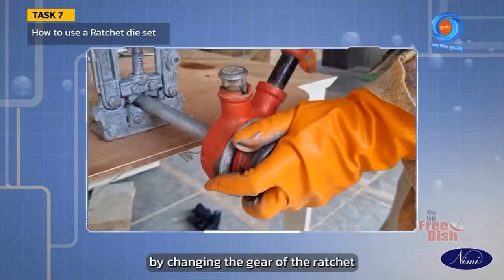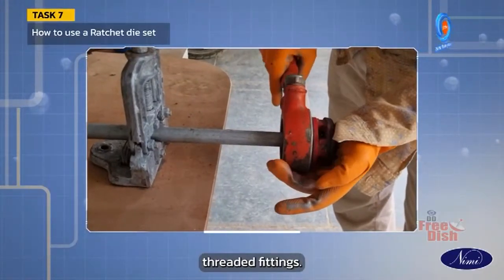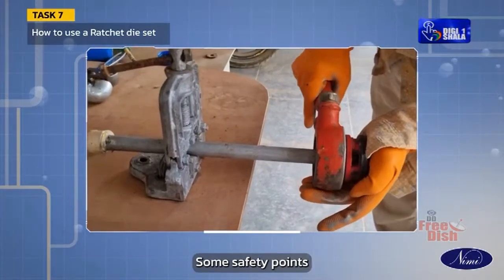Reverse the action by changing the gear of the ratchet die stock. Check the threads using female threaded fittings. Use lubricant oil frequently while cutting threads. Some safety points to remember.